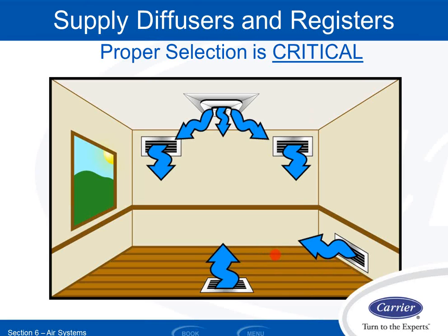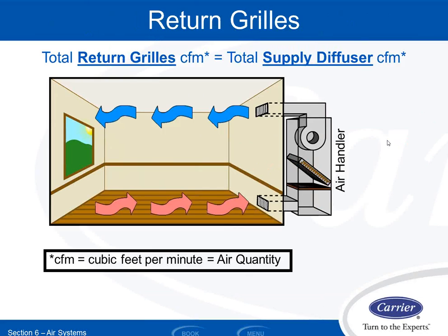So the ventilation codes, ASHRAE Standard 62 and IMC, penalize you, and those codes require you to bring in 25% more outdoor ventilation air if you don't follow certain rules, and one of those rules is no more than 15-degree discharge temperature above the space temperature. Other rules include how far you got to throw it across and down the wall, which I said was halfway down the wall, and I got an exterior, you got to throw it towards and away from the glass. If you follow those things, you don't have to take the penalty. I talked about that last week a little bit, but I didn't talk about it today. So in fairness to you guys, we need to cover that again.